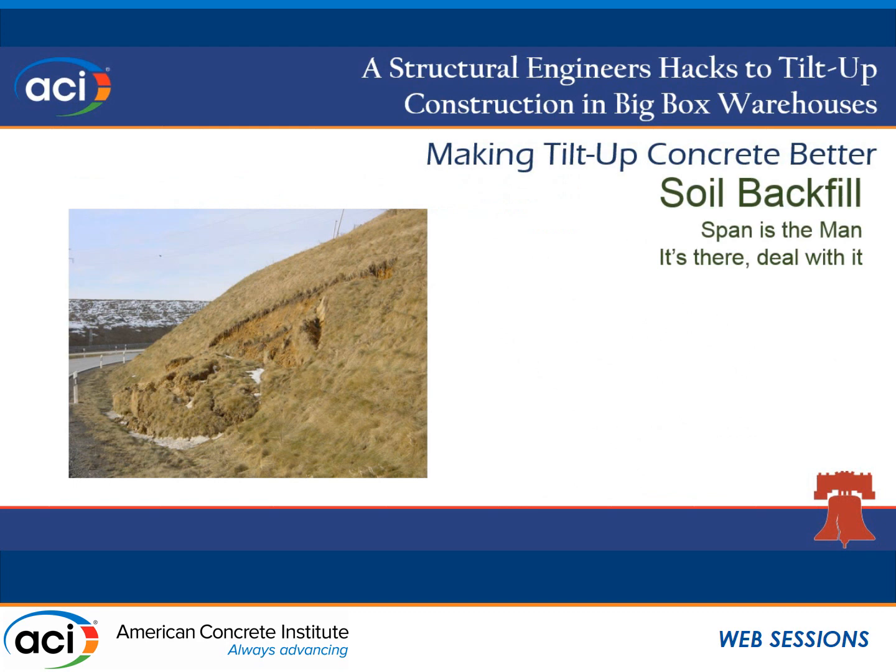Soil loads, I'll tell you what my typical behavior is, and that is, you know, the typical 4-foot tall loading dock panel, right? Your bottom of footing is 5 feet below finished floor, or your top of footing is. You can treat that as fixed, okay? But in doing that slab connection, you've got to account for the fact that you've got all that soil load there adding to it. So if you have, say, a high wind region or high seismic region where you're really counting on that slab connection to take the out-of-plane load, don't just stop your analysis at finished floor. Make sure you account for that reaction. Make sure you account for it as an at-rest pressure.